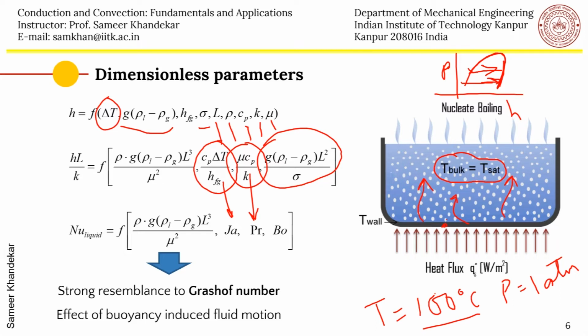When the Bond number is high, it means buoyancy is dominant, and when it is low, it is a surface tension dominant system. And then you also see another interesting non-dimensional number, which is the buoyant force divided by the viscous forces, which strongly resembles the Grashof number which you have studied in the lecture on natural convection. It is a very similar phenomenon happening here. There, hot air was getting moved upwards because of buoyancy, and the viscosity of the air itself was the force which was trying to stop it, creating the resistance.